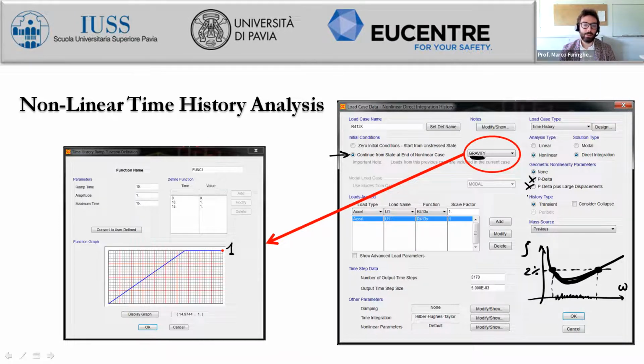I would say that for general applications for buildings, where we have rather small displacements, the P-Delta effects induced by the isolation devices can also be neglected, just because the foundation structures and the columns should be stiff and robust enough not to have particular influence induced by the P-Delta effects, and the same for the interface between the superstructure and the isolation layer.